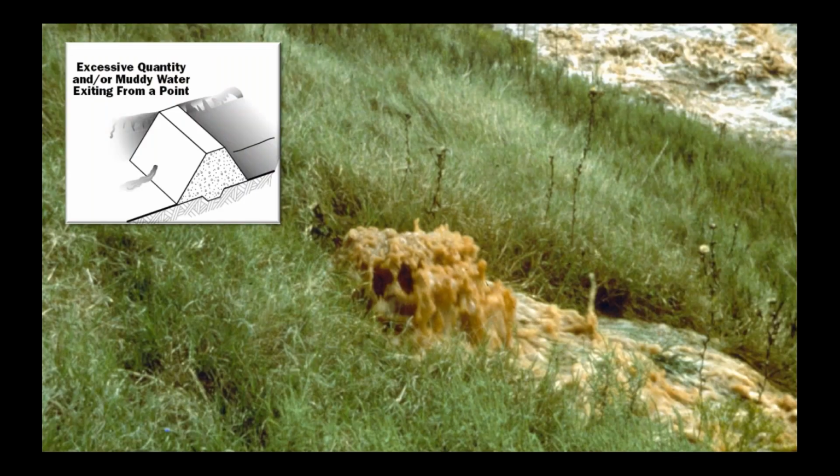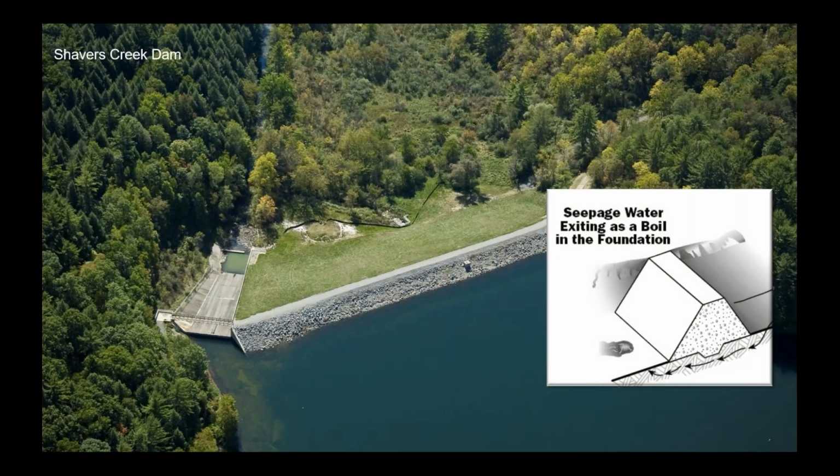And if you had any kind of seepage coming from the dam where it's muddy seepage, that is a serious condition. It means the embankment is being eroded, and probably the reservoir should be lowered and the dam repaired.